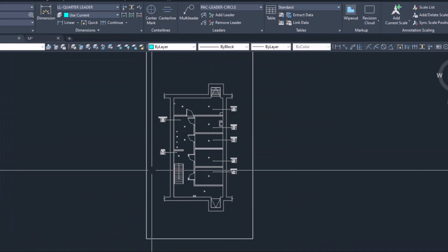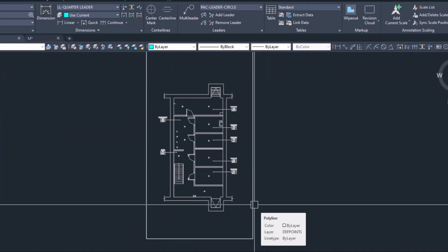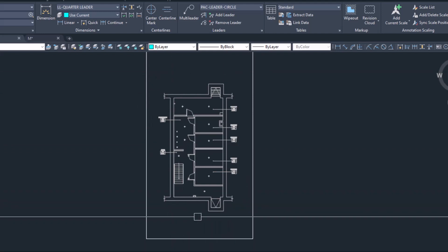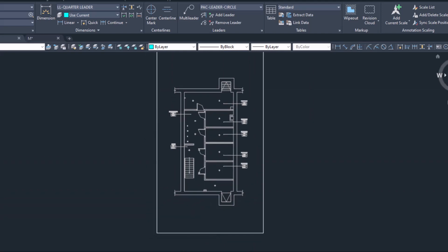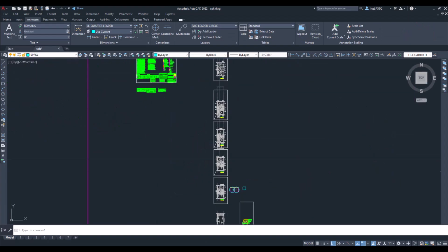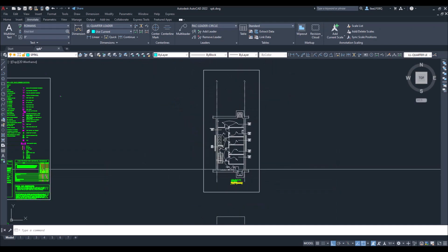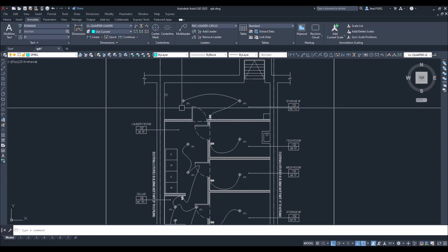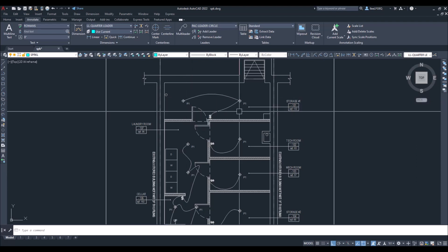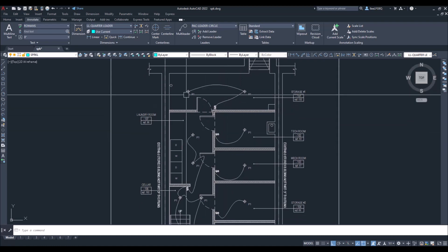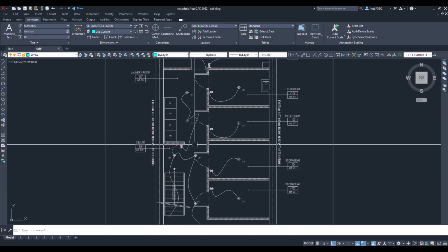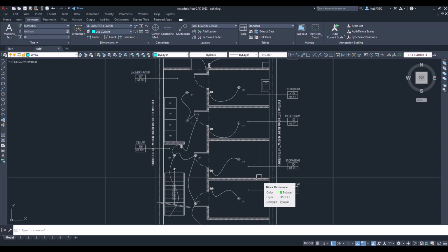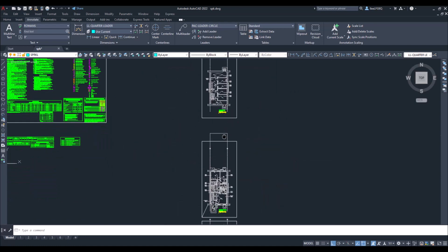I'm going to now go over the example in CAD, lay out the sprinkler heads, the piping, and go through an entire sprinkler design from start to finish. So let's begin. So here's a floor plan of our example. We have the cellar floor, and we need the RCP plan because whenever you design a sprinkler system, you should always have the RCP plan rather than the floor plan, because we need to coordinate the sprinkler heads with the light fixtures as well as anything else that may be on the ceiling, such as speakers or security cameras and things like that.